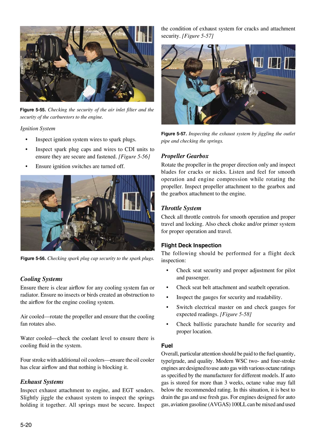Exhaust systems: inspect exhaust attachment to engine and EGT senders. Slightly jiggle the exhaust system to inspect the springs holding it together. All springs must be secure. Inspect the condition of exhaust system for cracks and attachment security.